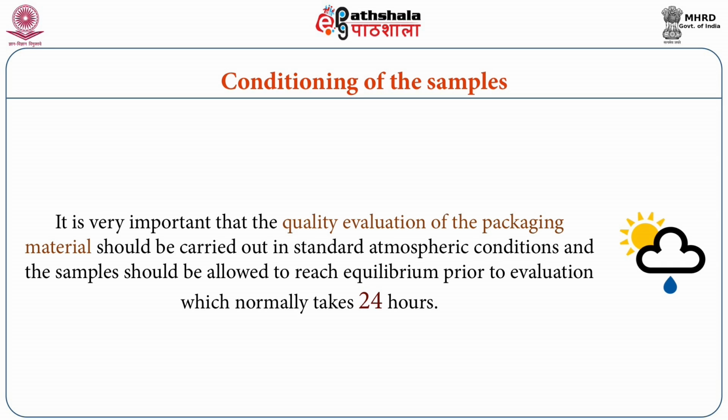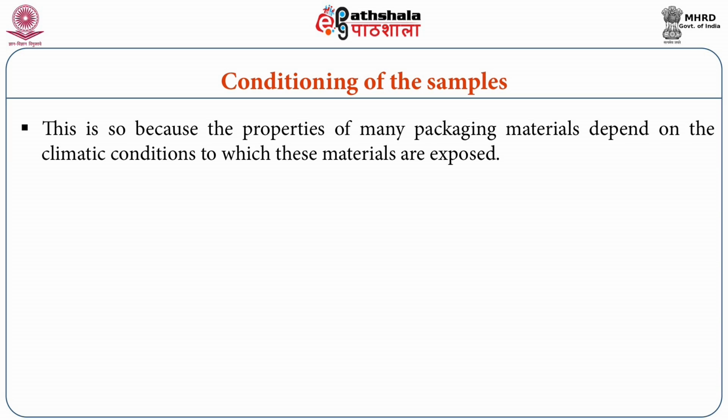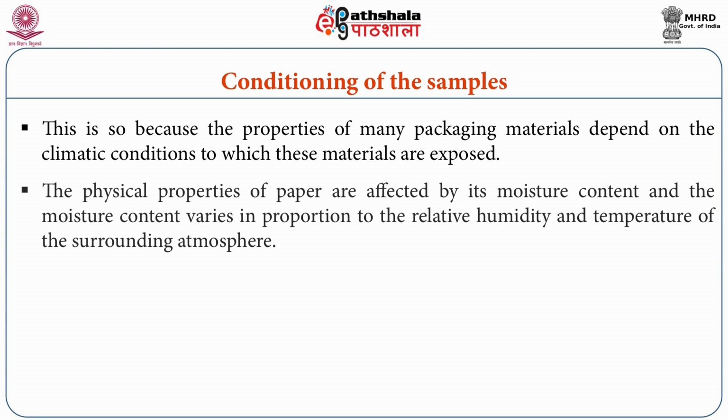It is very important that the quality evaluation of packaging material should be carried out in standard atmospheric conditions, and the samples should be allowed to reach equilibrium prior to evaluation, which normally takes 24 hours. This is so because the properties of many packaging materials depend on the climatic conditions to which these materials are exposed. The physical properties of paper are affected by its moisture content, and the moisture content varies in proportion to the relative humidity and temperature of the surrounding atmosphere.